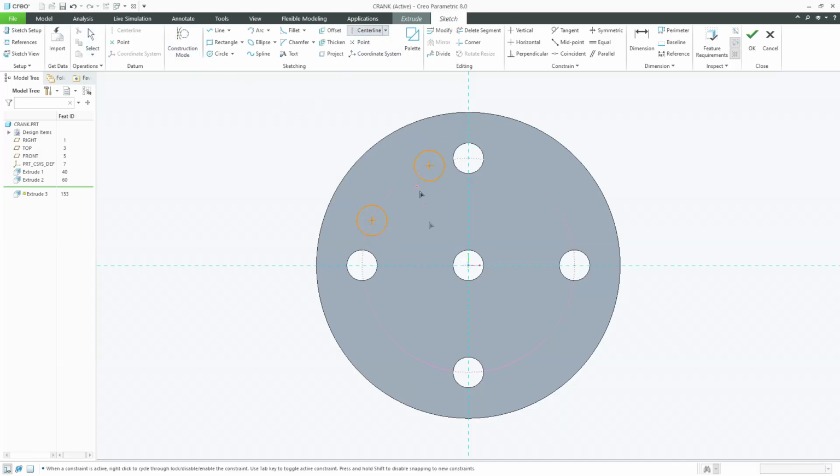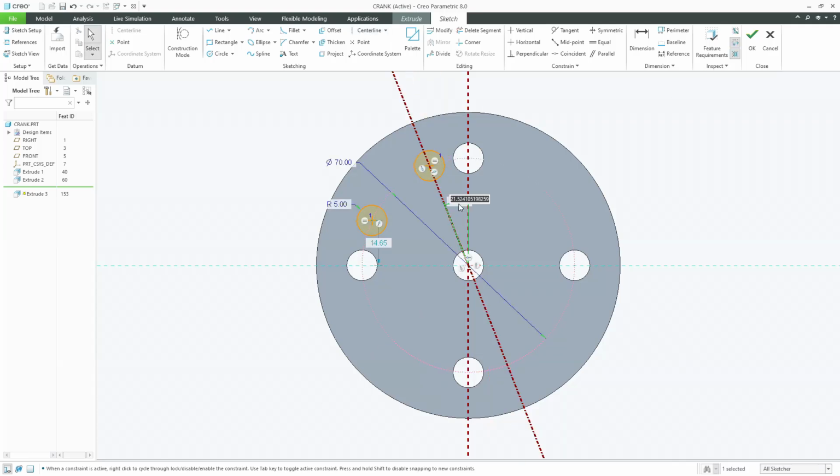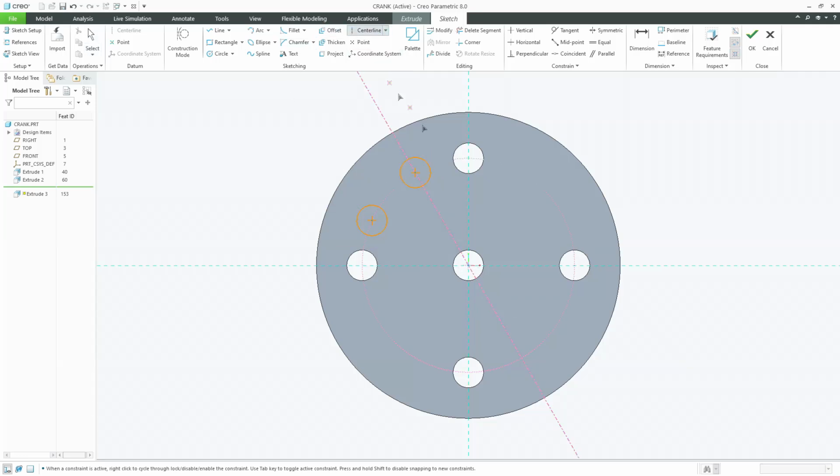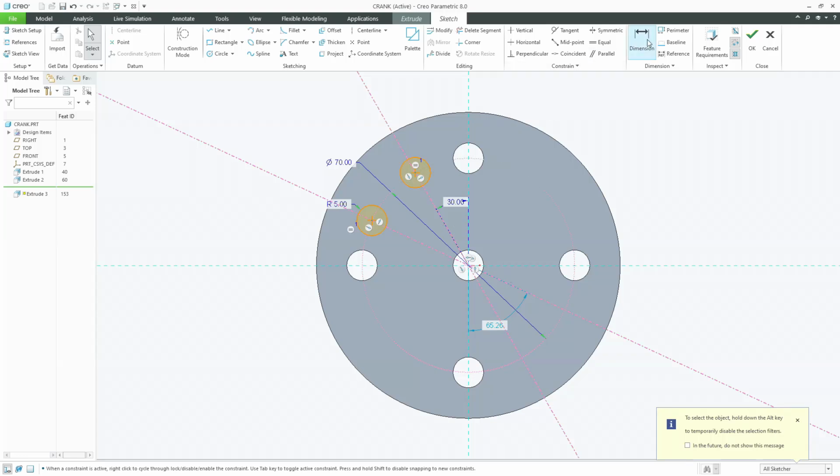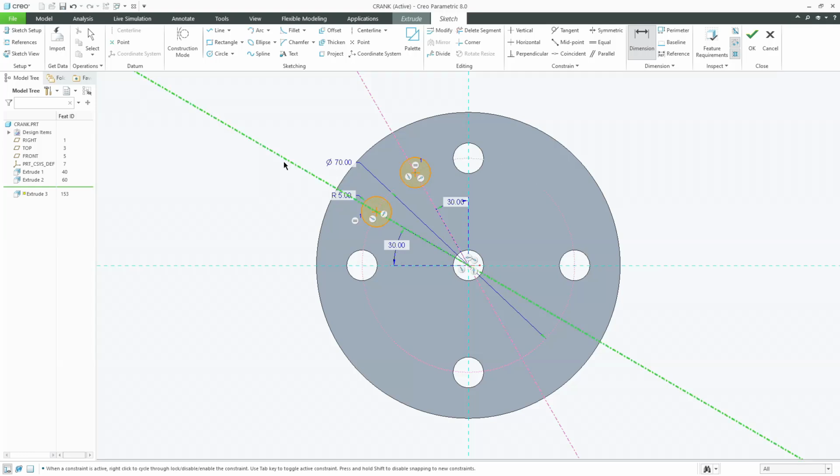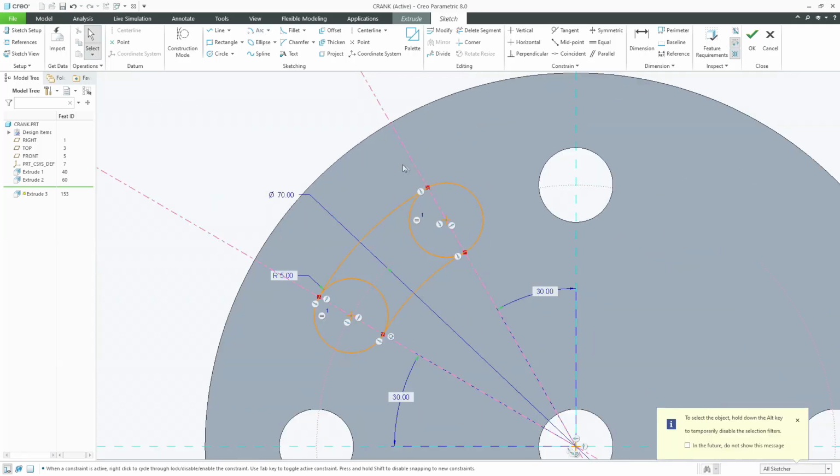The angle of this circle profile, I'm going to get coincident from the center line at an angle of 30° for both. And next I'm going to create a center point arc to connect the edges of these lines, same as for the bottom one. Then I'm going to delete all the unwanted lines here.